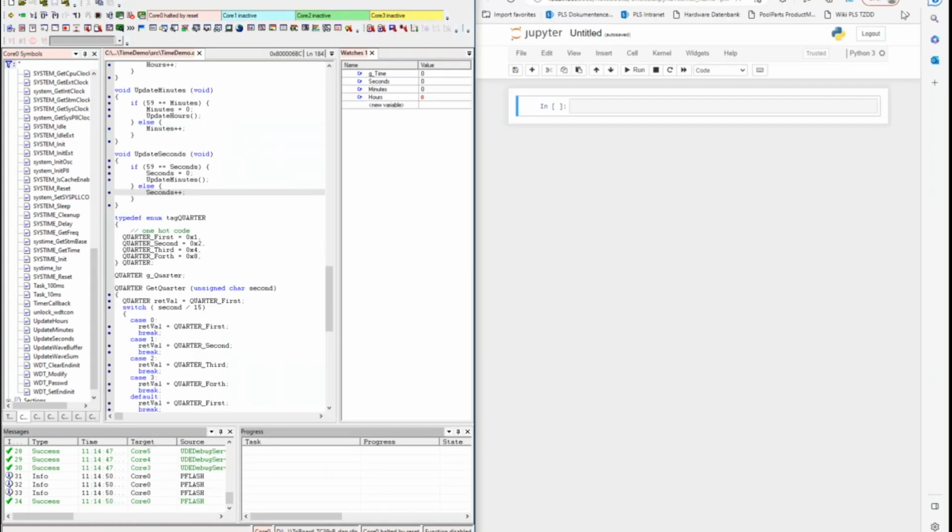Okay, then let me close that and show you how it works in the example. The first thing we need to do in every script is to load some libraries provided by Python. The most important one for us is the win32com.client library, because this is used to use the Microsoft COM in the Python script.